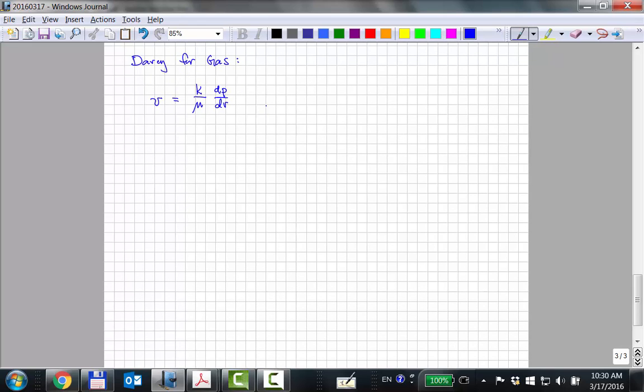We've got this equation. The velocity is equal to the surface gas rate, which I'm just going to write QG, times, we need it in reservoir rate, times BG. That will convert it to reservoir volumes over the 2 pi RH.